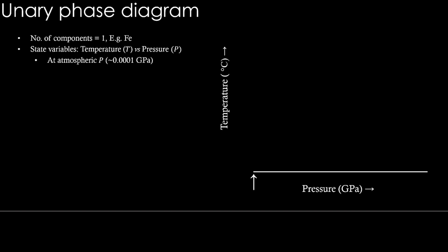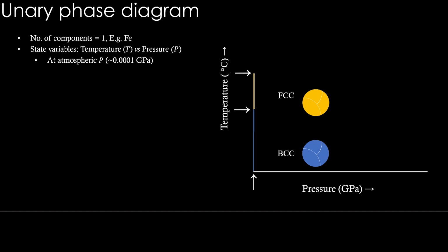At that pressure, at temperature of zero, it is in BCC structure. This is a schematic of its microstructure. So there are 3 grains of BCC. So what happens when the temperature increases? For a range of temperature, this BCC is stable. Then beyond a certain temperature, it becomes FCC, and it remains as FCC for a range of temperature. And this is the FCC microstructure. So once it reaches some other temperature, it becomes BCC again. So this is the BCC microstructure.